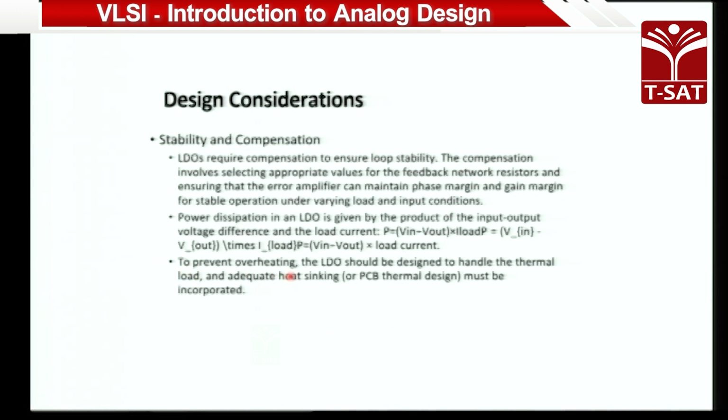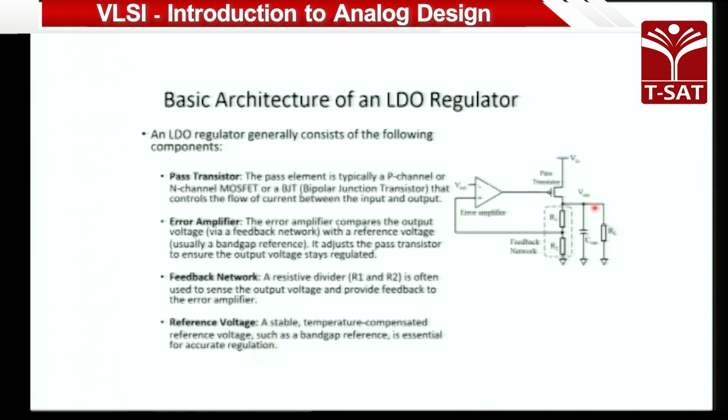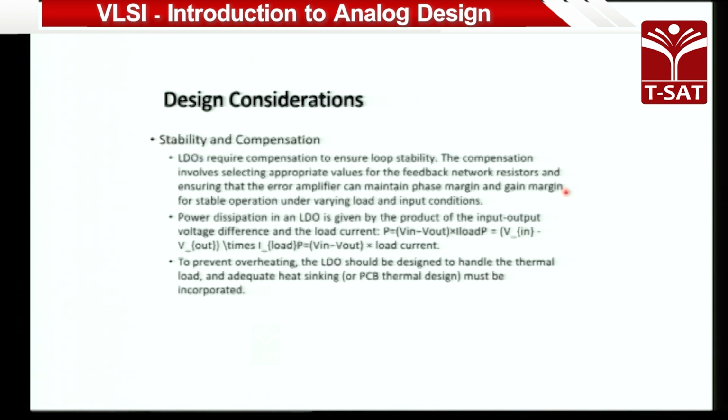I mean, definitely if the current that is flowing through this device is very high, right, this is the load, right. This load can be a big core, right. A core means like a digital core, maybe a high speed core, it is actually operating here, and this output is actually delivering current to that core. Maybe there are hundreds of milliamps of current flowing through this. So, that will actually create a lot of heat, and that heat can actually impact this device performance. So, you need to take care of that heat dissipation. You need to work on thermal management on that particular side.